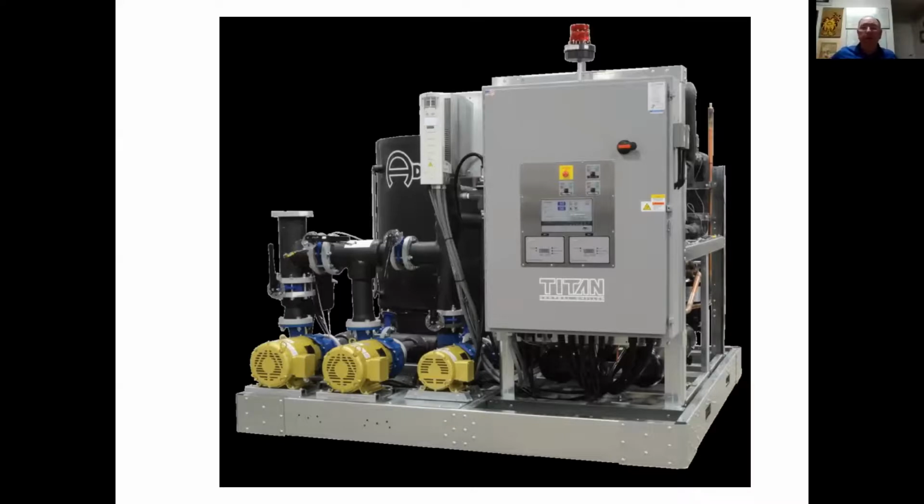Typically, the central chiller is going to incorporate one or two or more refrigerant systems or zones. And the control system is going to stage those zones based on your cooling needs at any given time. That cooling need is determined by the leaving water temperature going out to your process, and it's sending that temperature to the controller, and the controller is determining if it's at the set point temperature or if it's above or below, and then makes adjustments with the refrigerant circuits to maintain your set point temperature.